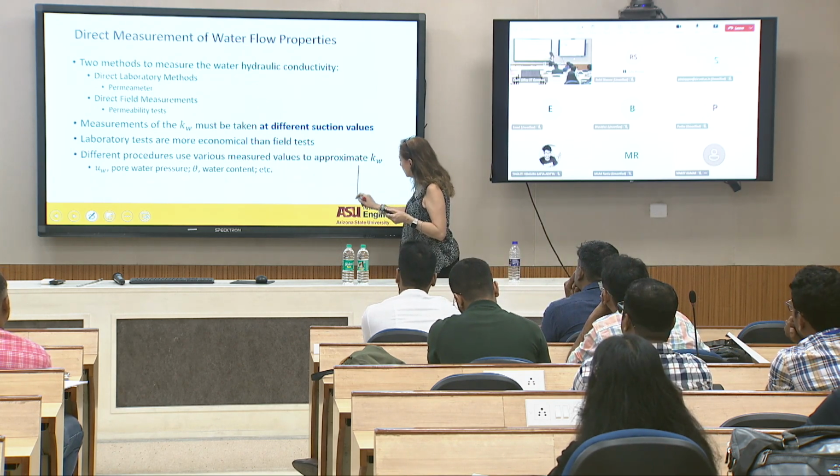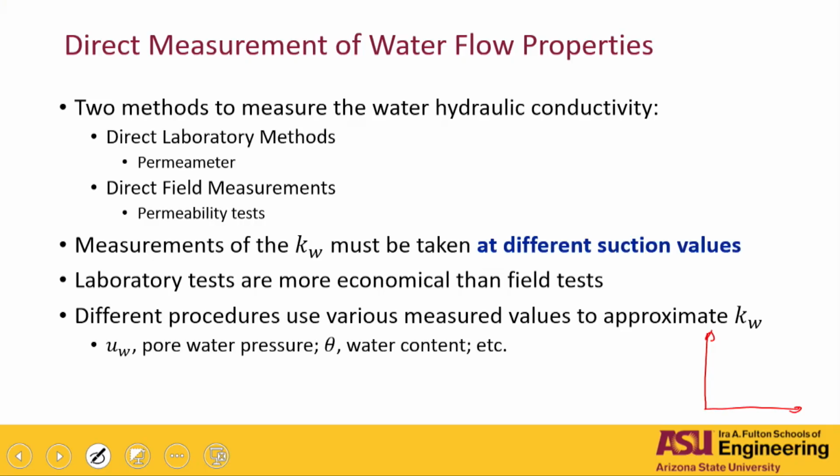Even if you can go for pore water pressure measurements, because of the high suction values, for example in the field, you're going to need a high suction tensiometer, which is very expensive. If you have low suction sandy materials, you can get tensiometers that are much cheaper. But if you cannot measure pore water pressure, then you're going to need to measure water contents, right? And then you go to the soil water characteristic curve and you just go back and forth. And then you can do a more fundamental analysis with the suction value.